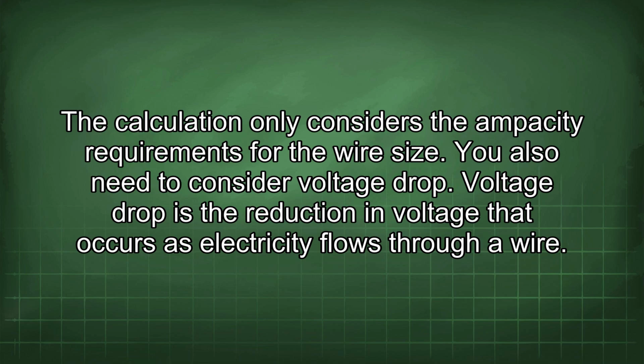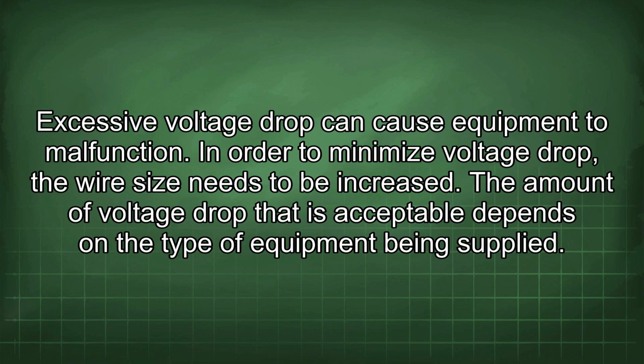The calculation only considers the ampacity requirements for the wire size. You also need to consider voltage drop. Voltage drop is the reduction in voltage that occurs as electricity flows through a wire. Excessive voltage drop can cause equipment to malfunction.